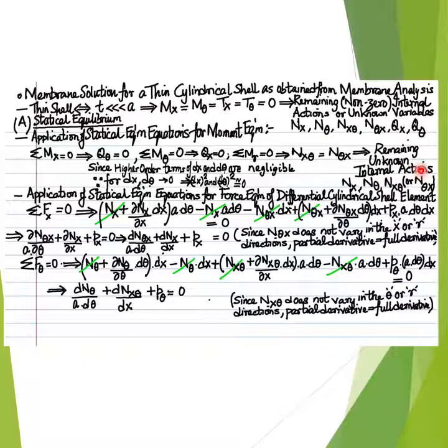Let us retain nx theta as the unknown internal membrane shear force, since the determination of nx theta will result in the determination of the complementary unknown internal membrane shear force n theta x by itself.